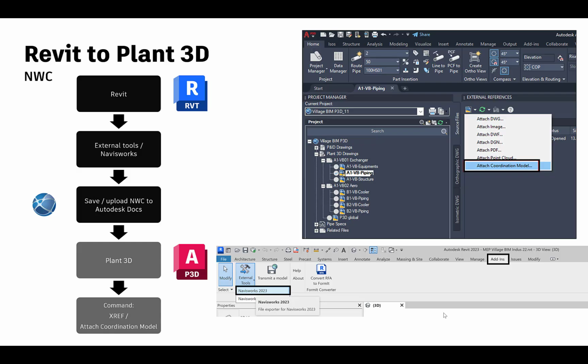Or if you wanted to bring that Revit model into Plant 3D, it comes in as a Navisworks cache file, and you just basically have to attach it as a coordination model.